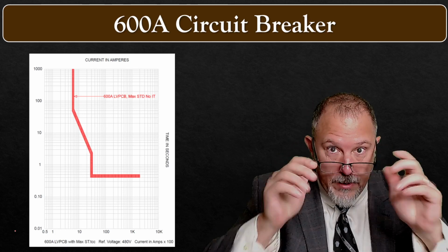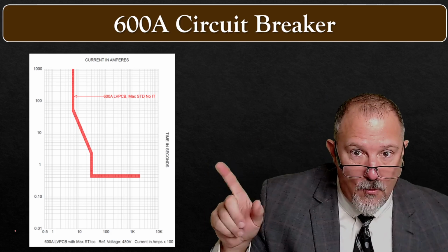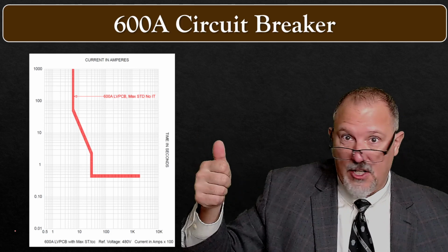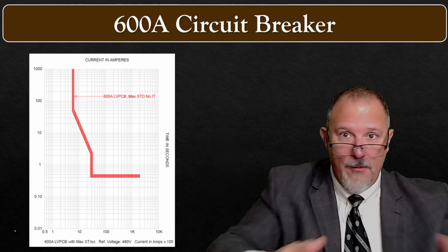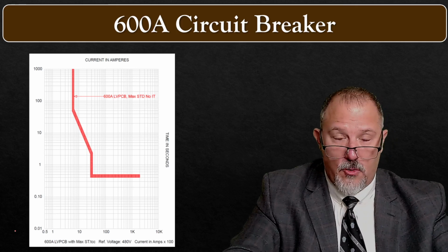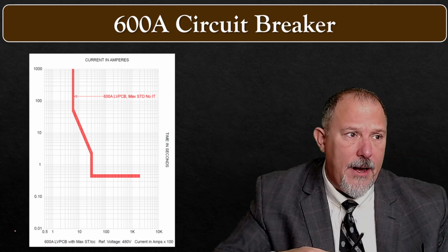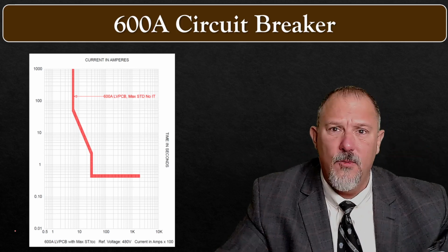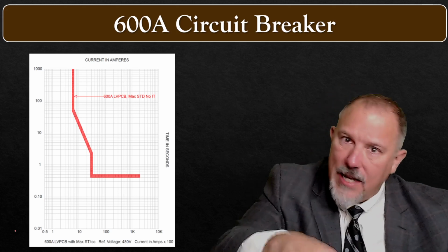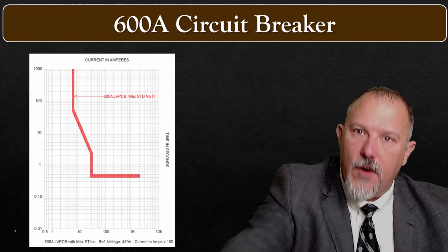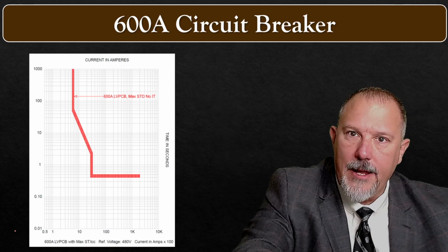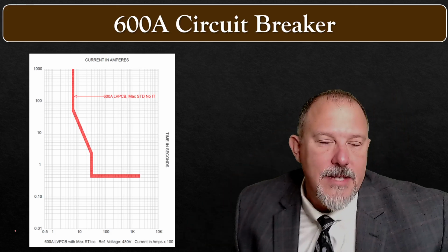This is what bringing beef to the table does for you. Why might I want this? Service entrance equipment. I want to ride through all the short circuit currents that are going on downstream. Why? Not because I just want to wreak havoc. No, I want the downstream devices to isolate the faults locally and not take out the main.